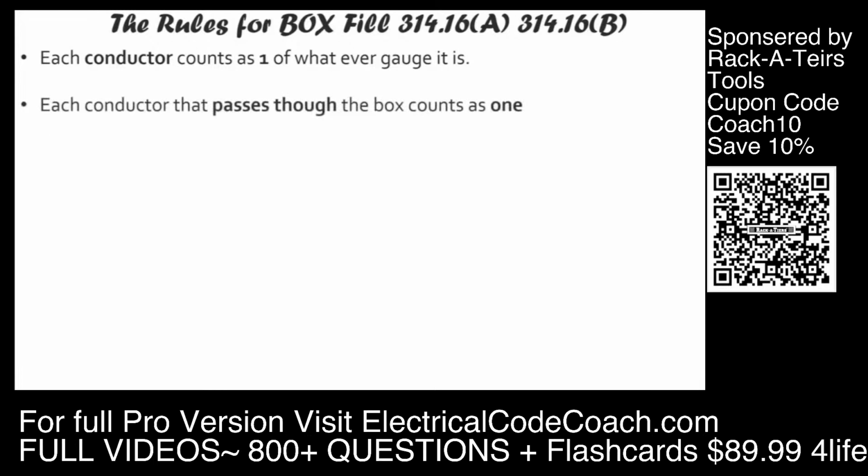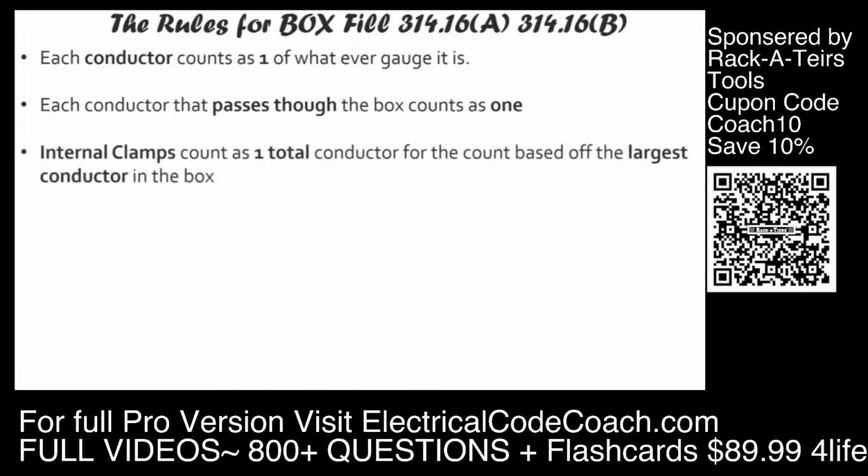Each conductor that passes through the box counts as 1. So even if it doesn't terminate or splice inside that box, if it's passing through that box, it counts as 1 each. Each internal clamp only counts as 1 total based off the largest conductor that's in the box.